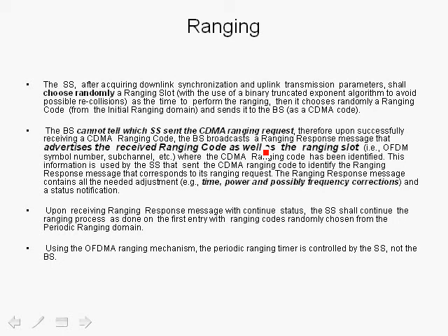However, the base station also computes, for example, the required power for power control that it has to program into the subscriber station. It has computed the required timing offset to achieve time alignment and other parameters, for example, frequency offset. But it doesn't know what subscriber station actually sent this. So what it does is it encodes the ranging code that it has figured out, the CDMA code that was used, and it knows what ranging slot was used. So it sends that to all subscriber stations.